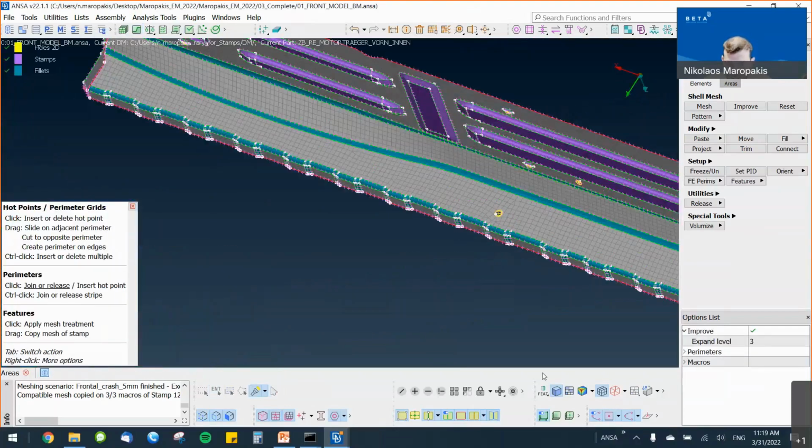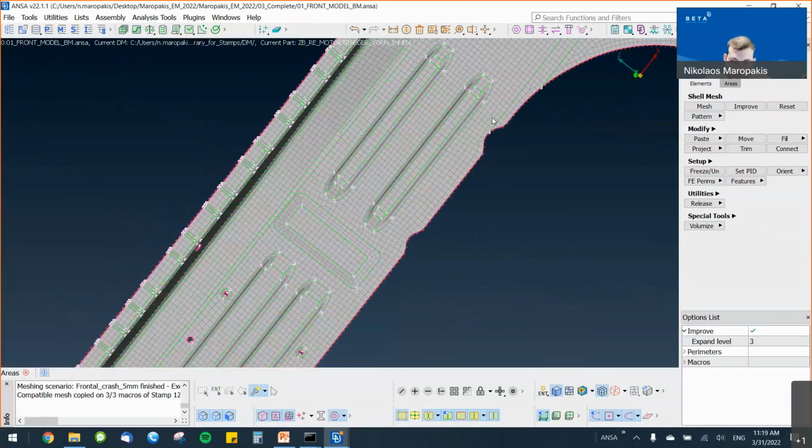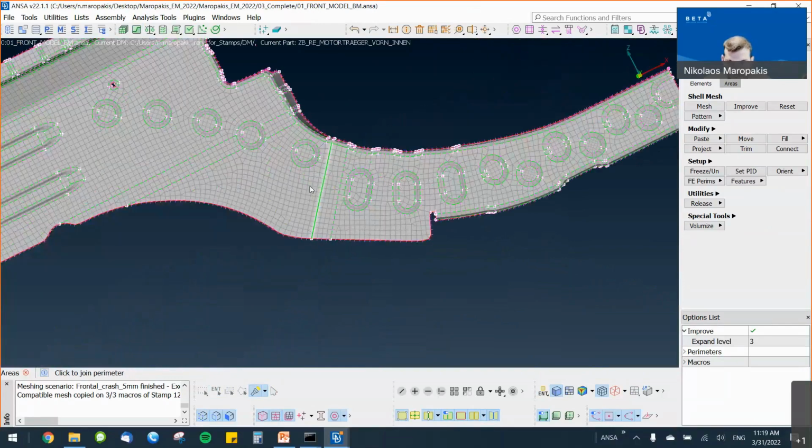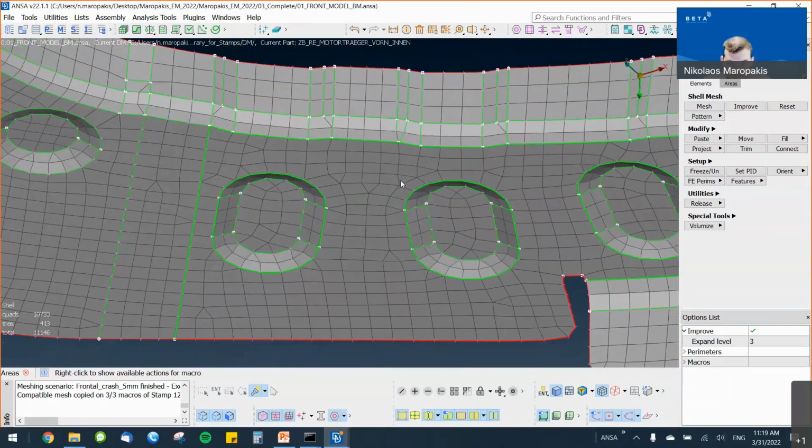Now let's combine all these things that we saw to try to fix a messy area. Let's improve the mesh of an area using only the direct edit functionality and keeping my mouse and the focus on the middle of the screen. Now I have the direct edit functionality here on the areas category, and I will try to fix this area here. I will perform a lateral cut here, dragging from this node to have a more uniform mesh.